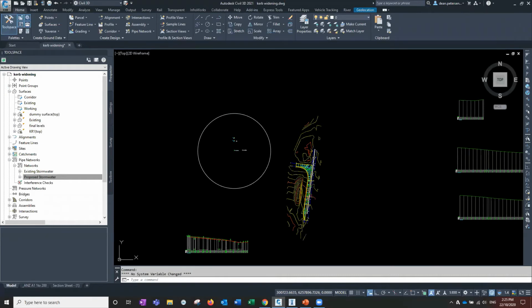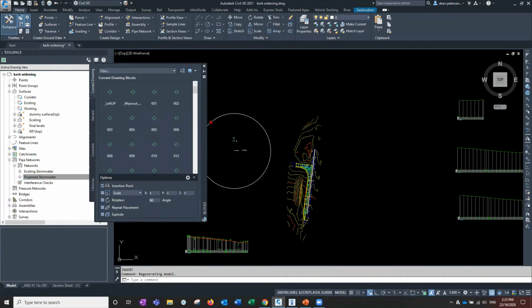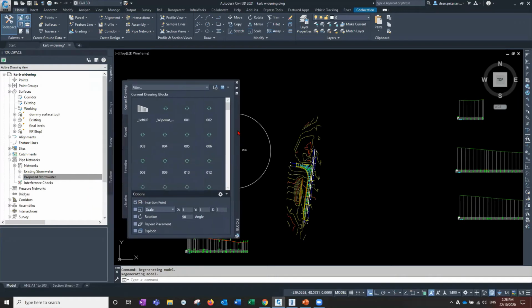So what we would do is go to the normal insert command in AutoCAD. So it's I, enter. It's up in the ribbon as well, but why not use the command line? It's nice and quick. And set up how we want to insert this data. So we want to not specify an insertion point. We want it in the same location that 12D had it, in the same coordinate system. We will explode it when it comes in. We don't want it as a block. We want it as individual elements. And don't want to rotate it.